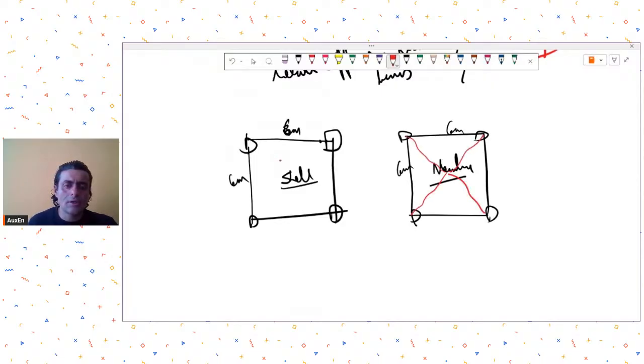In shells the load distribution will be on the basis of relative stiffness, because all the spans are the same and beam sizes are almost similar for each span. Almost similar load transfer will happen in this case whether you are using shell or membrane.